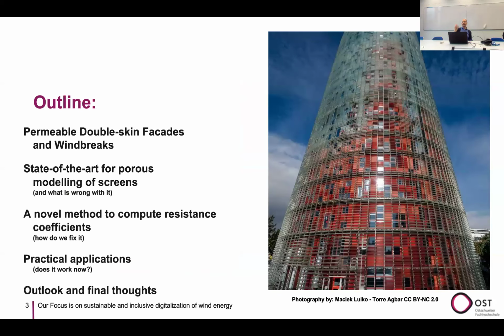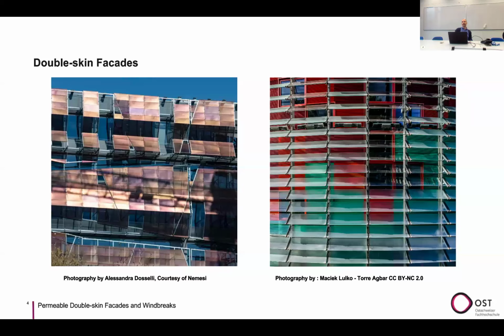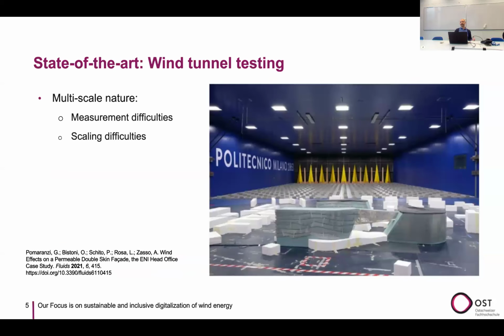Now, obviously, these are very big structures, and they have to be designed for wind loads. And currently, the best way we can design for wind loads, you can consider the golden standard, is to do wind tunnel testing of different structures. So you put a scale structure in the wind tunnel, and you let the wind blow on it, and you measure the pressures, and there is some procedure for how to do it properly.